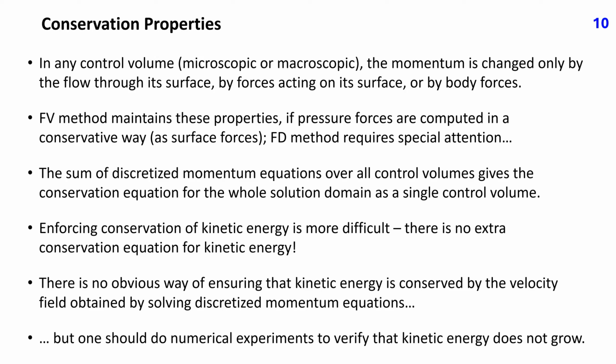In conservative methods, the sum of discretized momentum equations over all control volumes gives the conservation equation for the whole solution domain as a single volume, because all surface integrals over internal control volume faces cancel out in such a sum. Enforcing conservation of kinetic energy is also desirable, but there is no extra conservation equation for kinetic energy.